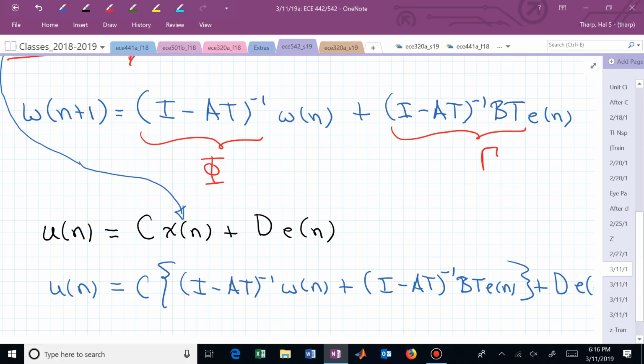So now phi is the system matrix in this state space representation where our state vector is W. It's not the original state vector X. If we want to make that connection, then we can pull it out with that last equation that I wrote down. If you need to know what X is, you connect it with the W using that if needed sentence.